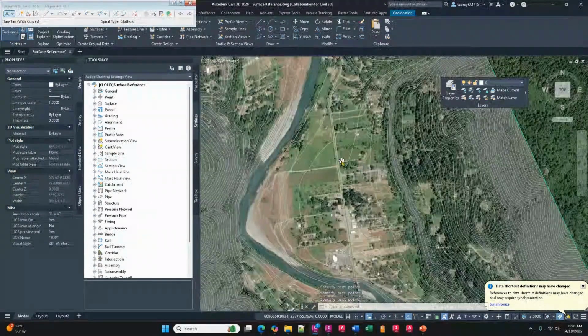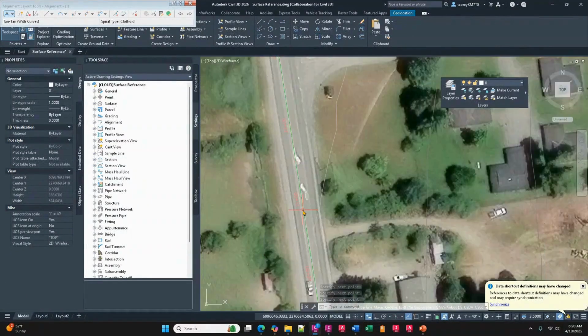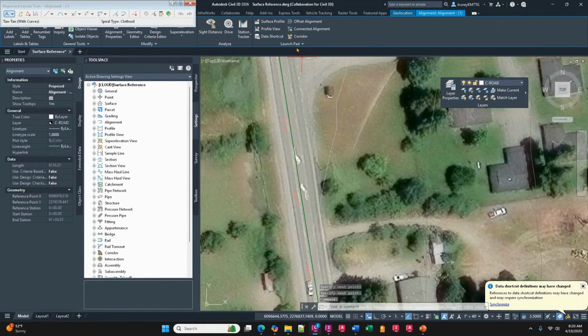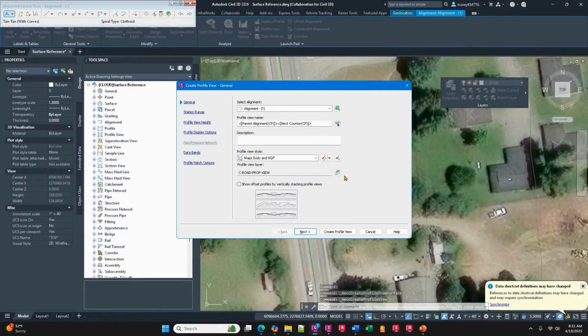Okay, so I do that. I'm going to go ahead and make an original ground profile of that, so a surface profile. And this is all stuff that's happening much faster because I was able to use Infraworks and share that huge surface out into the project and then consume it and clip it. They don't really use the term clipping, but partially open it, I guess, in Civil 3D right from that shared project.